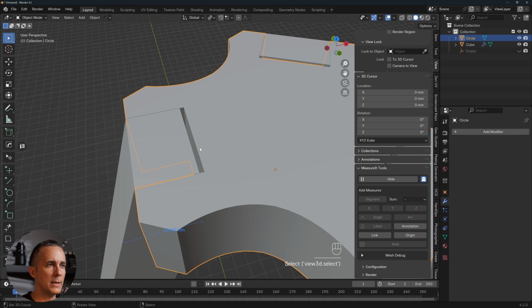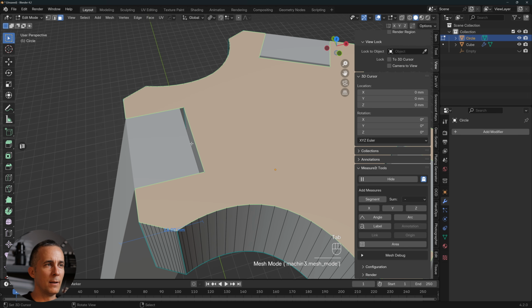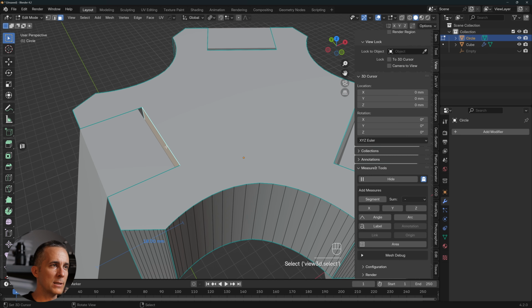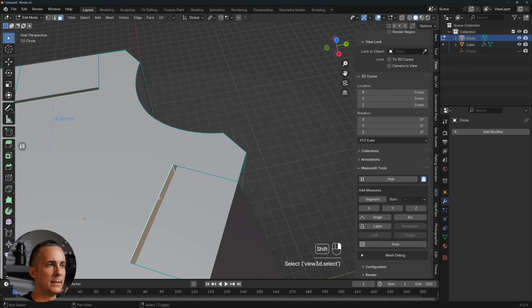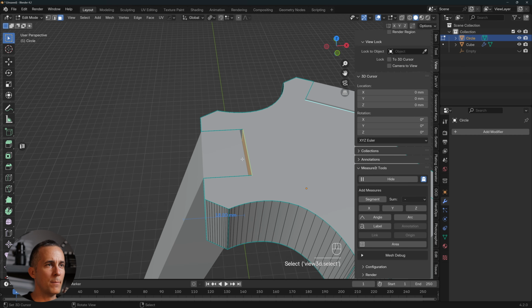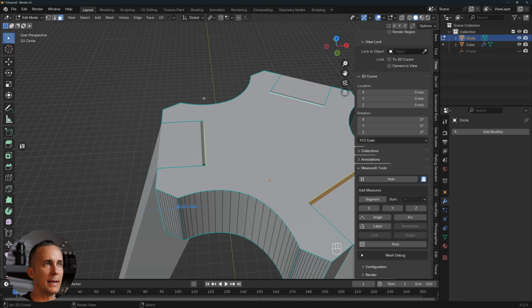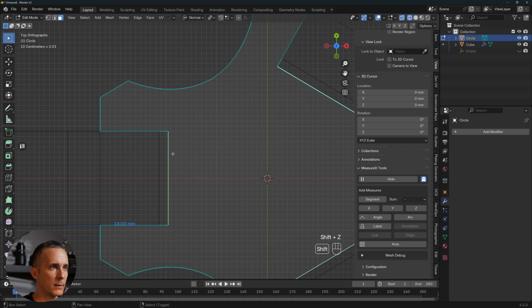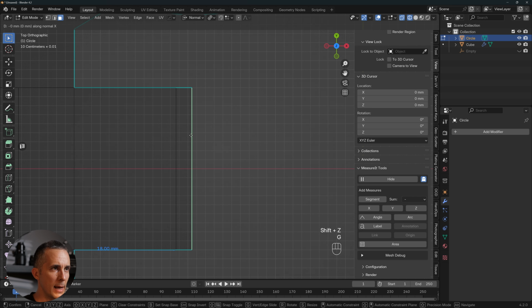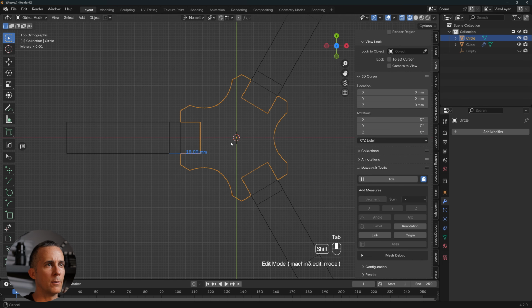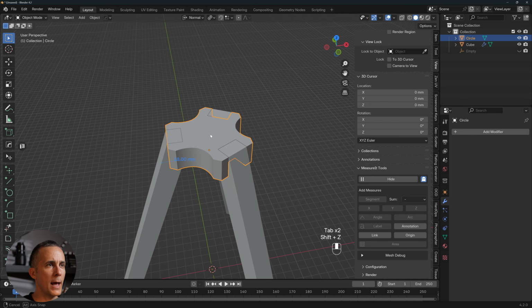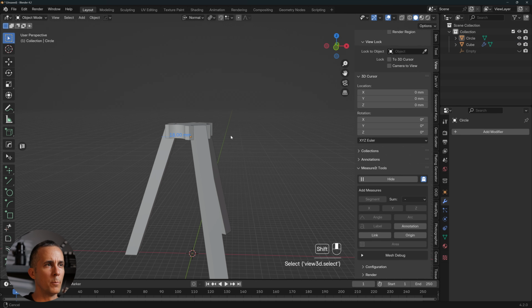Now what we need to do is go select this middle object, this holder, and I will select this face, and this face, and I want to expand them to touch this leg here. So I want to go from global here to normal, and I want to go with X-ray mode, GZ, and go right there. Perfect. So this is it. This is how it looks. Let's go back to normal mode, and this is really cool, part of our lamp.